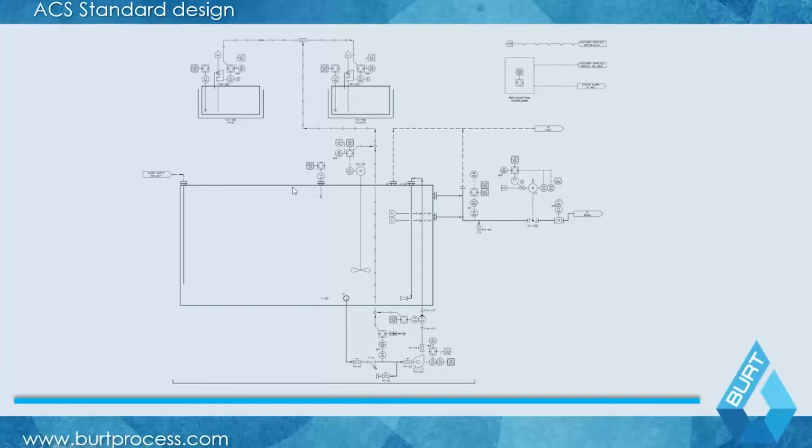If the waste in your neutralization tank is out of spec, this valve here will close, and then you have this additional freeboard. As an option for some larger systems, you can also have a diversion valve here, which brings the flow back to an equalization tank or lift station to make the system go into a full recirculation mode. In this case, the reagents are not dripped into the tank, but are put into a recirculation loop, which you see here, which basically educts it back into the mixer.